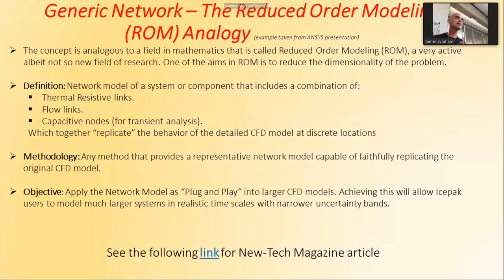After it does that, it doesn't do the simulation anymore. You can open the reduced order model viewer, which is free, and you play with the boundary conditions, okay? You change the boundary conditions according to the range of validity that the ROM was made for, and you can see how the results change in each and every component. And it's a linear process.